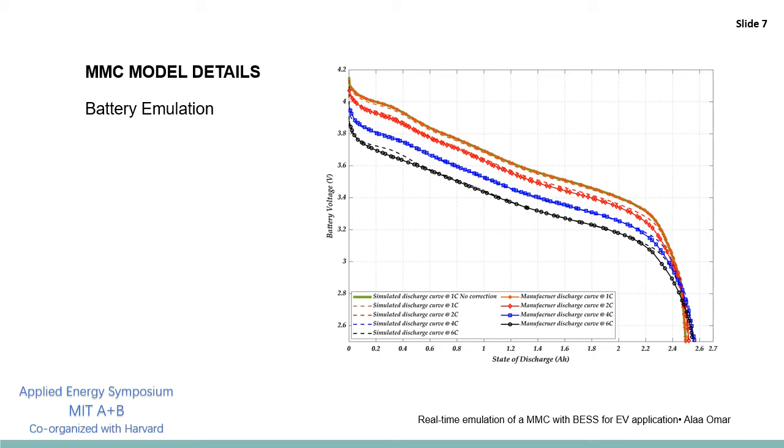These curves are for discharge rates at nominal battery current and at twice the nominal battery current, which is 2C, and 4C and 6C. Actually, during the discharge test, temperature changes from the start till the end of the battery discharge test. So, in the following hardware in the loop model that has been presented in this paper, the temperature is assumed to be constant.